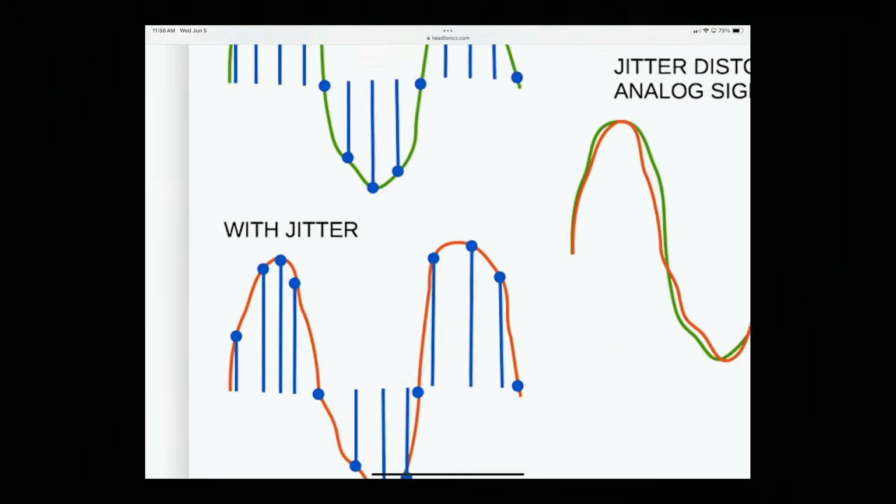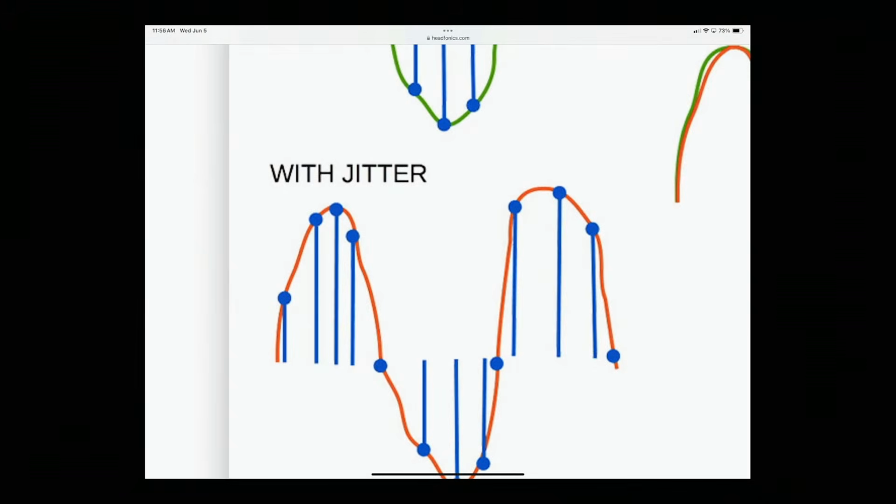You see down in this side that those blue vertical lines are not equally spaced, and so we're actually capturing the waveform at a different time. If that happens in the analog to digital conversion, it is forever stored in your audio, because you've captured the wrong time, and therefore you've captured the wrong level. So that's where power supply often creates sample clock timing problems.